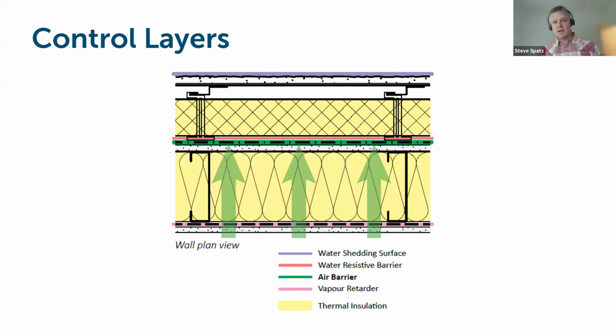In looking at this as a section view of a wall assembly, just breaking these down into defined locations. So the purple layer there at the exterior, that's going to be our bulk water control layer. Behind this is a continuous insulation, outboard insulation wall assembly. So we have a thermal control layer, thermal insulation, continuous insulation over what would be the WRB integrated with the air barrier.